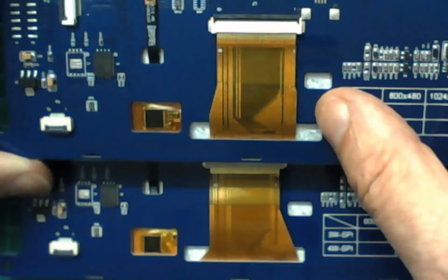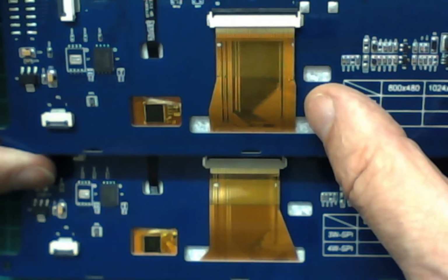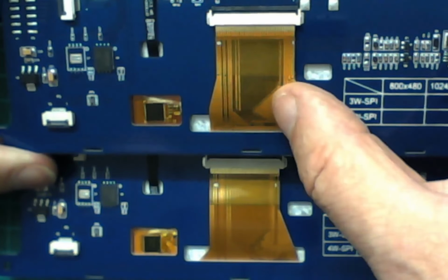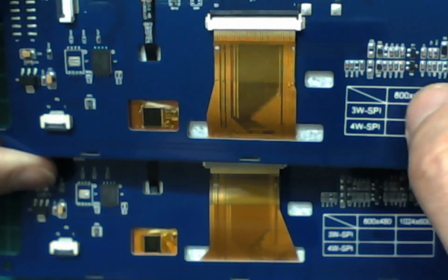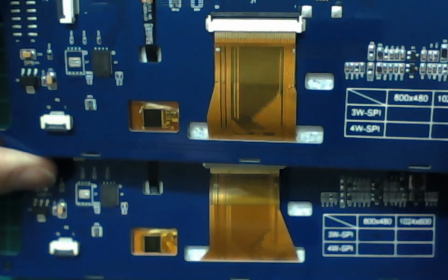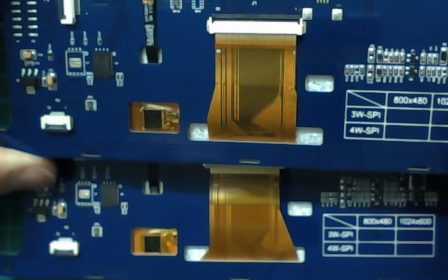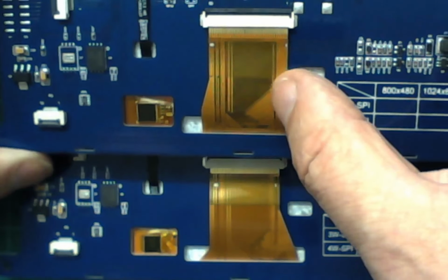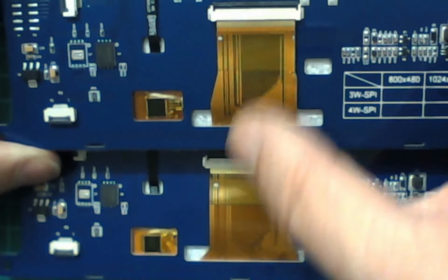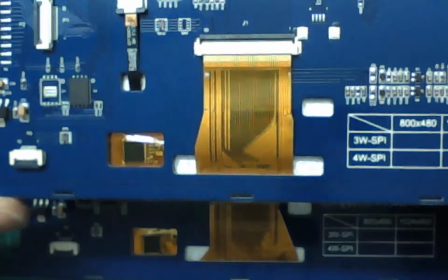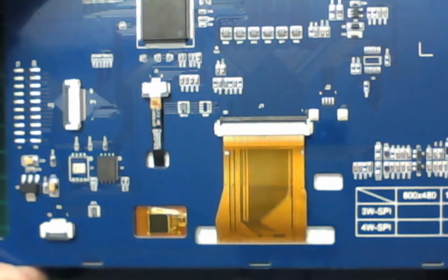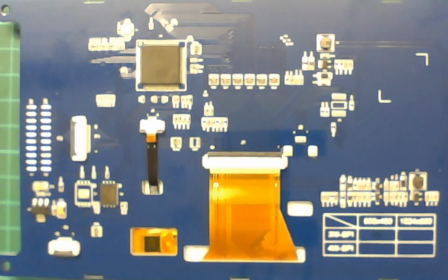That is the difference. You can see there's a slight difference in the ribbon cables, and that means that one is an 800 by 480 and the other one is a 1024 by 600, and on that web page it shows you which one's which, and it's quite important you know which one's which when you initialize them. Apart from that, they look identical. Okay. Why am I showing you a PCB at this point? Because I knew what was coming,